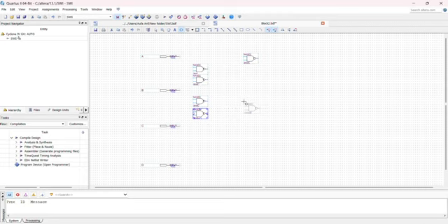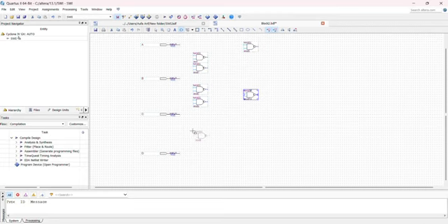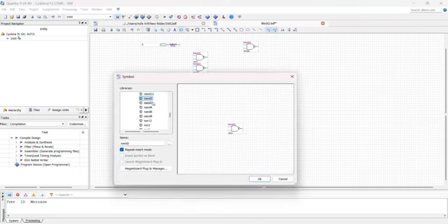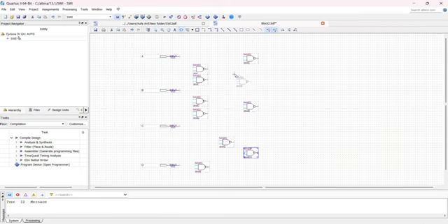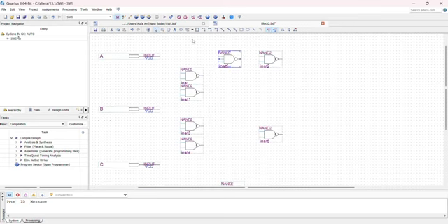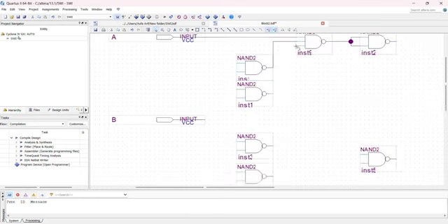For example, when you connect one input to a NAND gate, you can invert that input. So we'll use this property to simulate our logic gate. We'll place those 10 NAND gates, and we'll connect them to our outputs. And then we will connect these inputs, logic gates, and outputs according to the sketches.